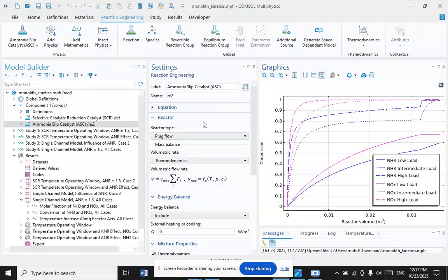chromatographic efficiency. These suites of examples illustrate the modeling of selective NO reduction that happens as flue gas passes through the channels of monolithic reactors in the exhaust system of motor vehicles. The simulations are aimed at finding the optimal dosing of NH3, the reactant that serves as reducing agent in the process. Three different analyses are performed.